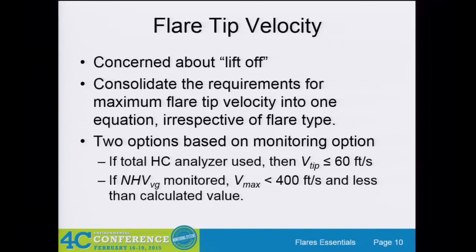Flare tip velocity. In the preamble to the proposed changes, they spent a lot of time talking about how they're very concerned about liftoff. They're not very concerned about low velocity coming out of the flare, but they're very concerned about high velocity.